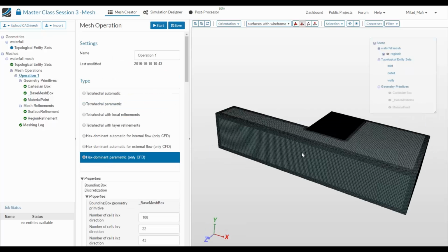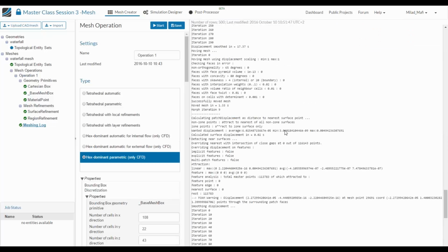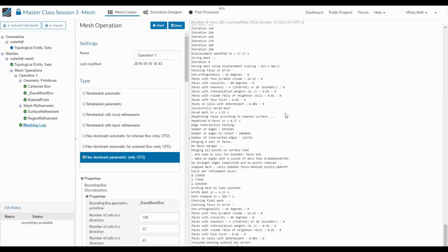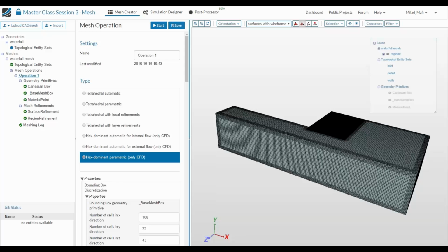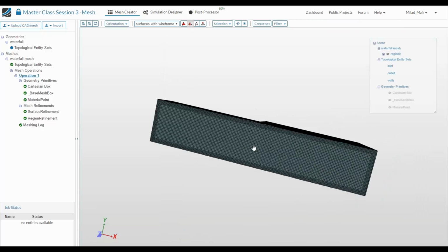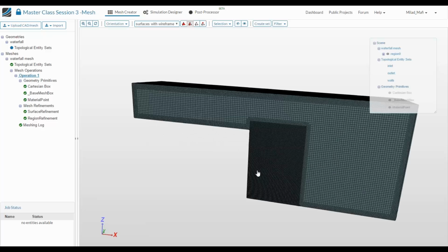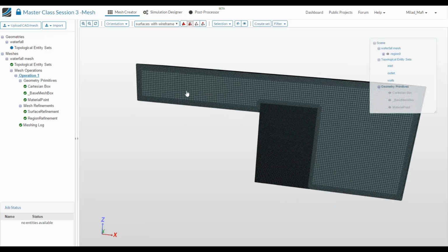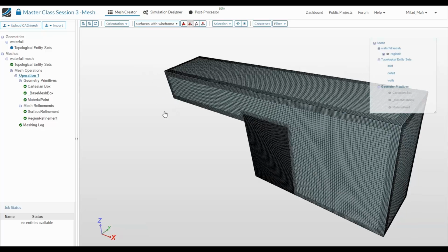And the final mesh, if we take a look at the log file, needs 320 seconds to be computed and some additional time to copy it. And what we'll do right now, first of all, we'll take a more detailed look at the mesh. And here you can see the refinement zone, which was applied automatically. And let's take a look inside the mesh, creating a mesh clip filter.